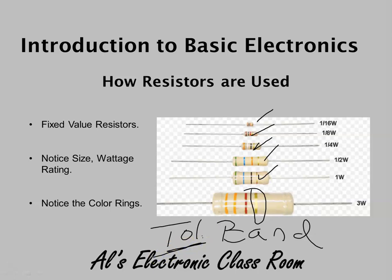Okay, the tolerance band is the specification on the resistor. In other words, that resistor may not be exactly the published value of the resistor, which is determined in this case by the first 3 bands right there. All right. So there's a tolerance, plus or minus 5%, plus or minus 10%, plus or minus 2%.